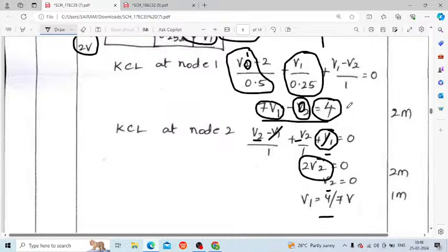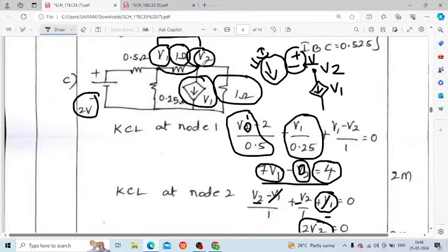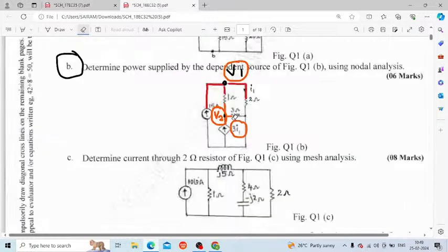Right? You got this problem? Okay. So if a node voltage is there and a dependent source is attached to it, what you should do is write the node voltage directly as the dependent source. You need not divide that node voltage by the resistance because there is no resistance, there is only a dependent source, right? In the same case, here is a node voltage V2 and here you have a dependent source, that is current dependent current source 3I1.